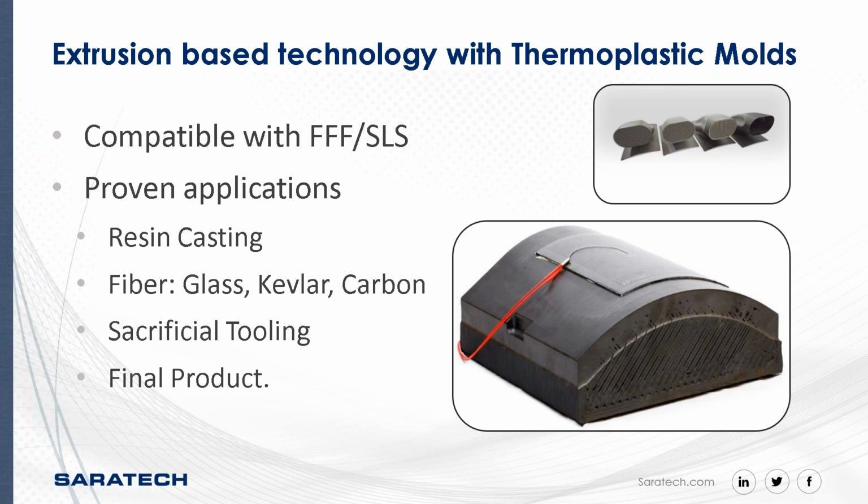The part you see here at the bottom was created by an FDM and took about an hour to print and additionally 4 hours to machine, then subjected to an autoclave with temperatures as high as 350 degrees and pressures of 90 psi. This was part of a Boeing spec process that is used to cure aerospace grade composite parts, and traditionally the lead time is as much as 14 weeks. This process, which is used in additive and subtractive technology, significantly reduces manufacturing costs and energy requirements by accelerating production times.